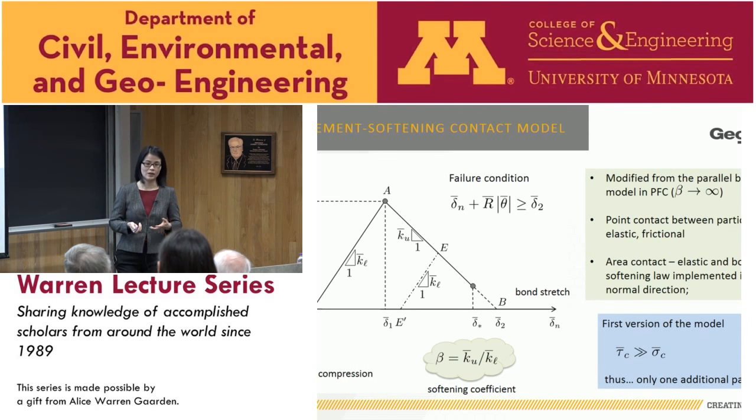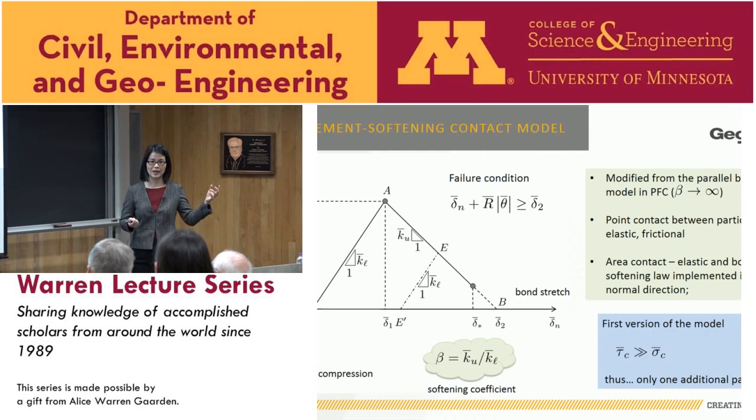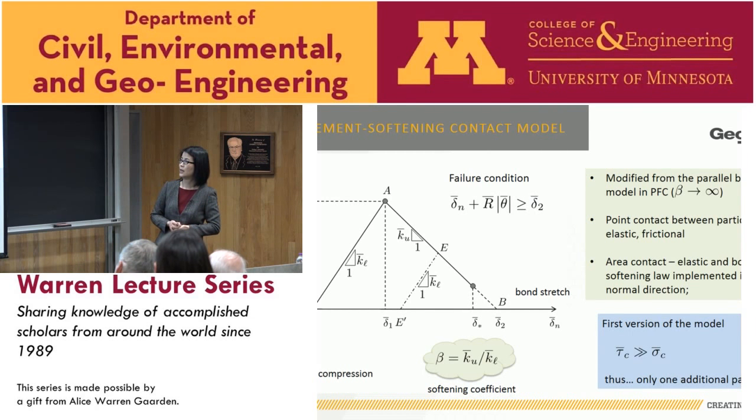We know that with more softening, you get higher toughness. Back then, we never thought about how the softening would affect the compressive behavior. We never made the connection between the compression test and the softening behavior. We were always thinking about process zone, softening, and therefore toughness, trying to get something out of the tensile strength.